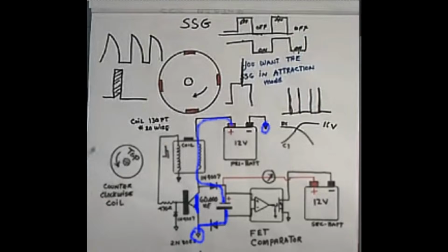He has, from the battery, he puts the plus here and the minus here on the coil to charge it one time, and then it flies back inverted polarity like so, plus and minus on the other side. And that same plus now can go through this diode again into this capacitor, the flyback.